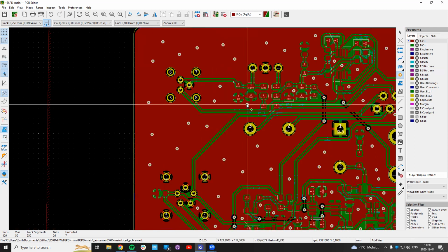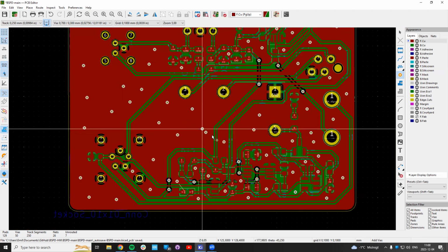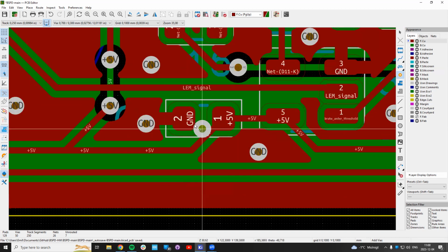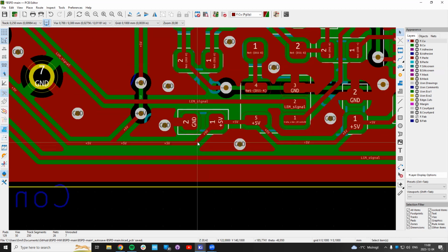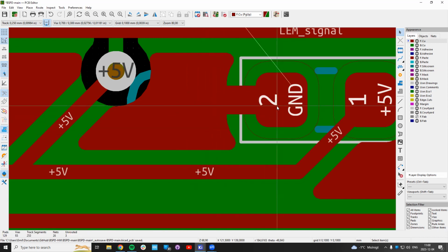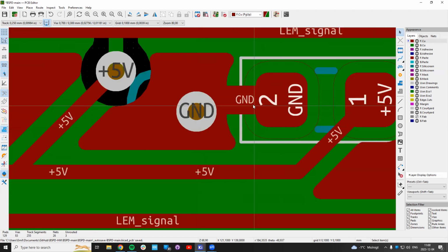Okay. How do we think this looks? Here we still have an issue, so place it there. And the trick is, if you get complaints, sometimes it doesn't just allow you to place a ground here and everything is fixed. A little tip is you route a trace out to a via, and that can sometimes fix your issues.